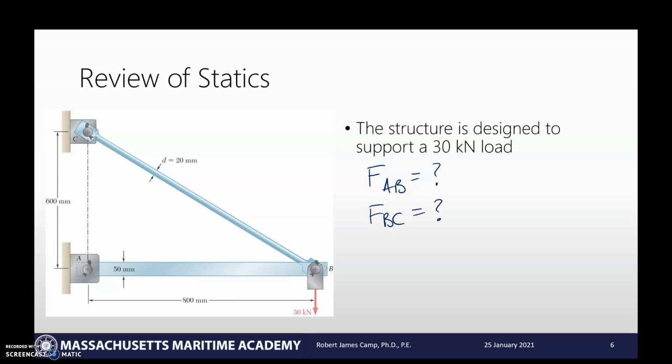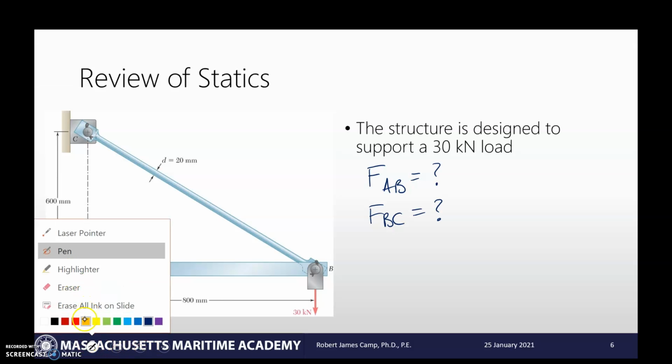So what we need to do is find the force on the inside of these different beams. The way we do that is we review all the external forces, set up a situation where we can use the equations of static equilibrium, and then make cuts into the material to find out what the internal force is. The first thing we need to do is draw a free body diagram of this structure, and identify the external forces.